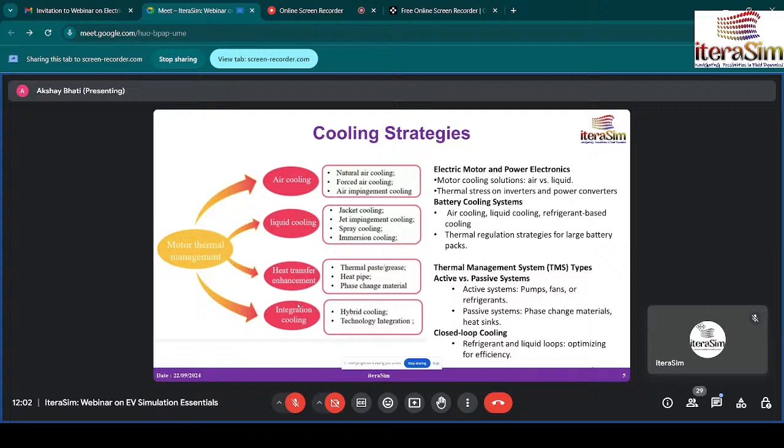And in this, we can also cool electronic components, but we have to use some dielectric oil. The oil should be electrically non-conductive. Water is electrically conductive, so in this zone we have to use some dielectric oil in the electronics cooling system. And another one is, one of the advantages of it, that it is space saving.